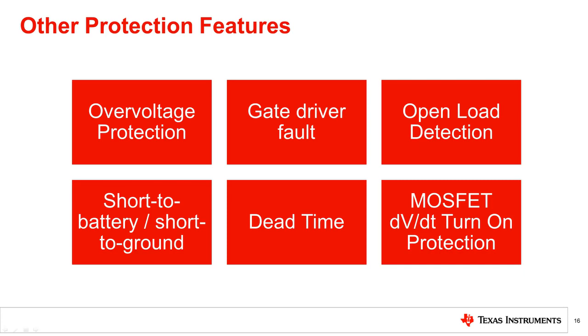Dead time is a feature implemented on TI's smart gate drive architecture. The motor driver continually turns on and off the FETs in an output phase, so both FETs must be off to avoid shoot-through current conditions. To implement this, digital dead time is automatically inserted to protect the integrity of the FETs, gate driver, and the motor. Furthermore, Smart Gate Drive can also protect the MOSFETs from accidental turn-ons through intelligent monitoring and driver actions.